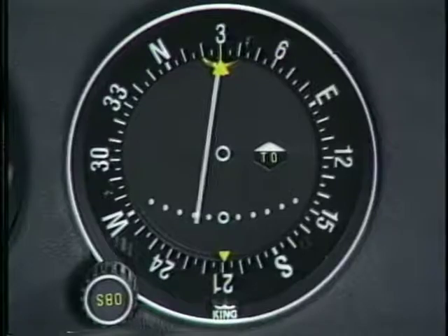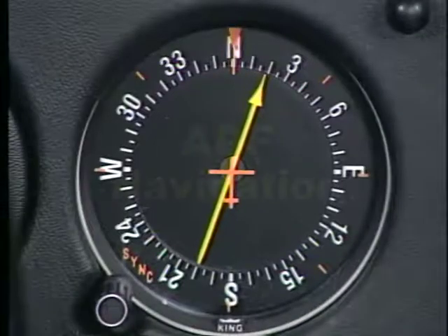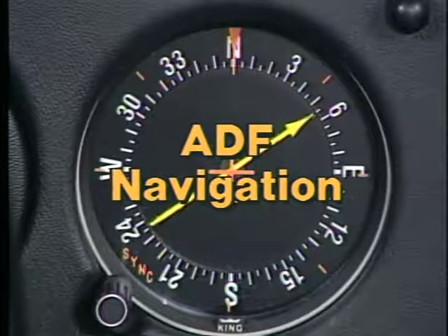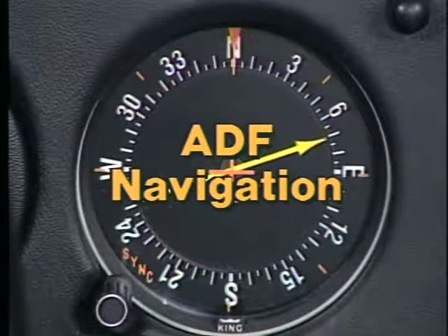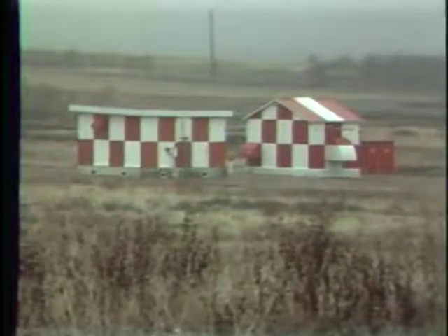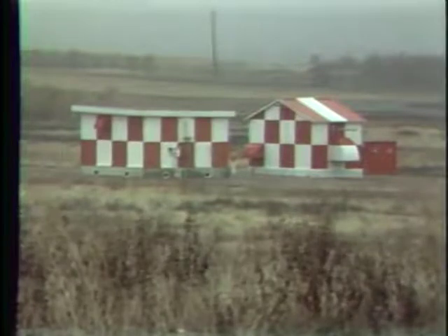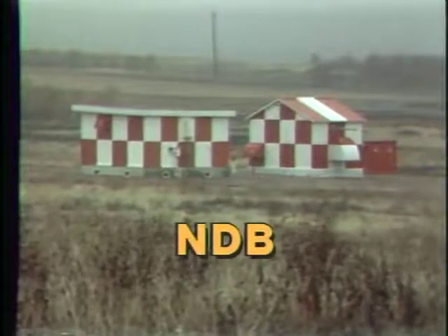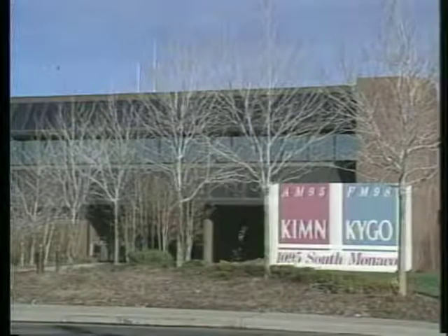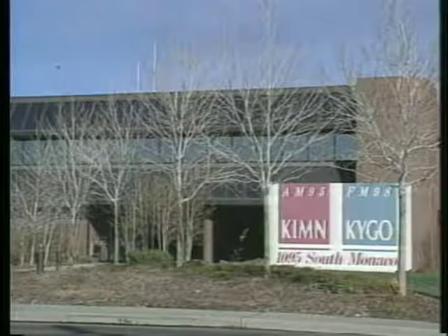In the last section, we looked at how to navigate using VOR. In this section, you will be introduced to the Automatic Direction Finder, which is referred to as ADF. Several ground facilities transmit signals that can be received by your airborne ADF equipment. The most common facility is called a non-directional radio beacon, or NDB. Certain commercial broadcast stations can also be received, but they should not be used as your primary source of navigation.